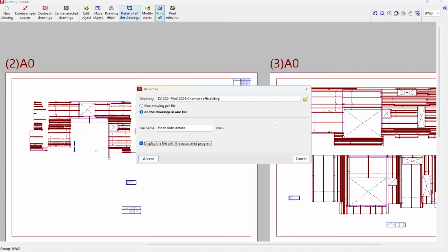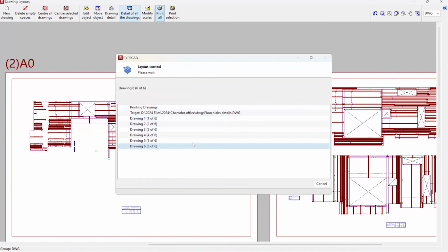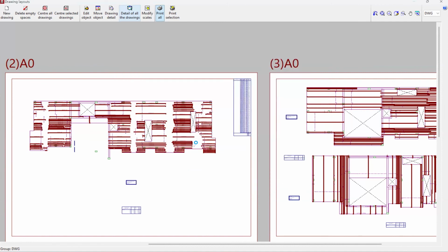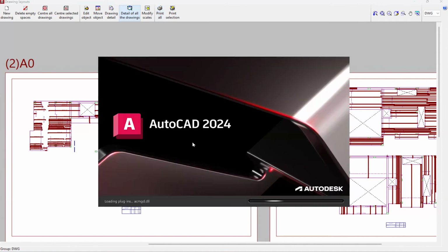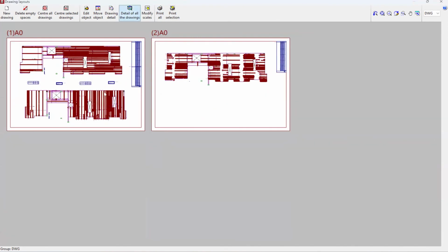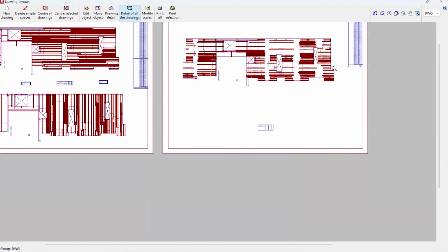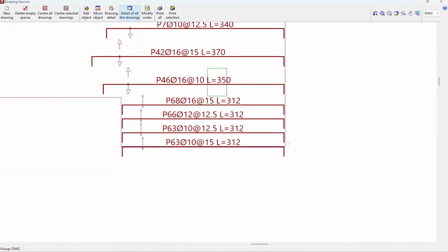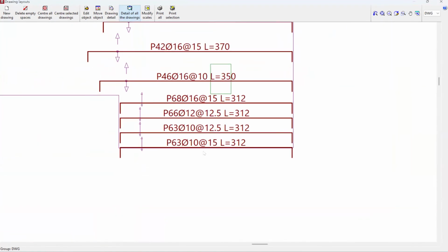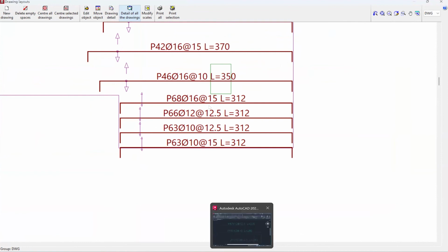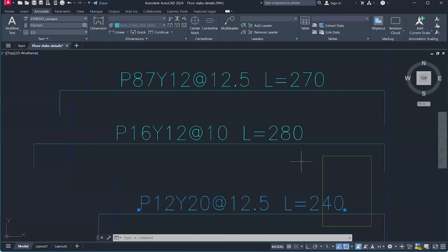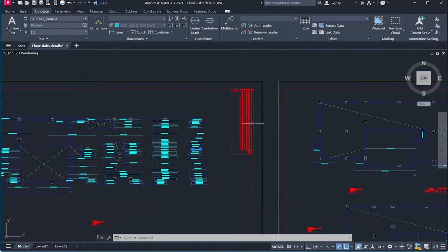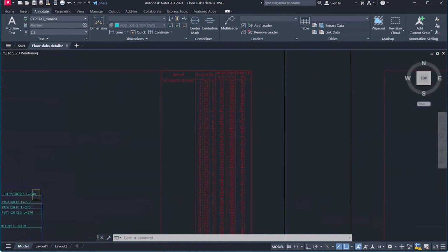You don't need to go back, so if we click here, we'll see what's going to happen. It's just going to recognize. AutoCAD will all open automatically, like now it's opening. So on this one here, it may still show centimeters, but once imported to AutoCAD, it will automatically change to millimeters. Then you'll have it properly in millimeters, even on the bending sheet as well.